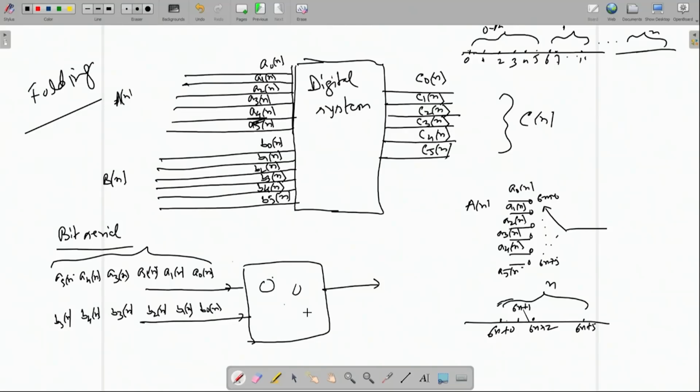Now, these two are the opposite, extreme ends. One is fully bit parallel, therefore word serial, where you pay in hardware and gain in speed. Another is fully bit serial, where you gain in hardware, because your hardware is 6 times less and power is 6 times less, but you lose in speed. Now, there is something in between called digit serial.